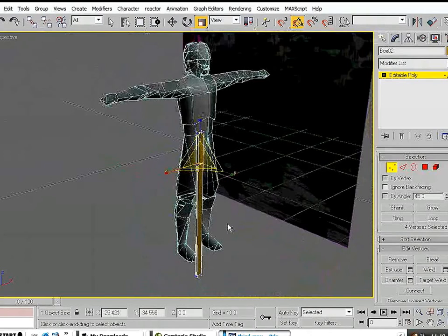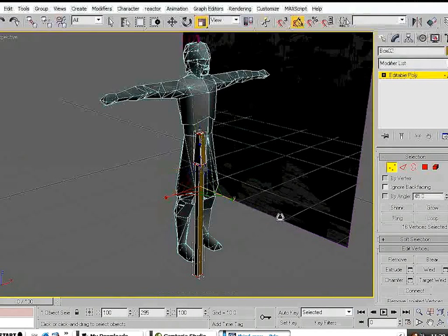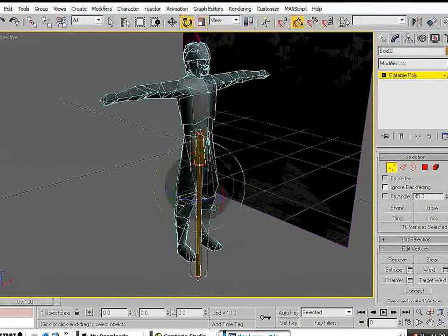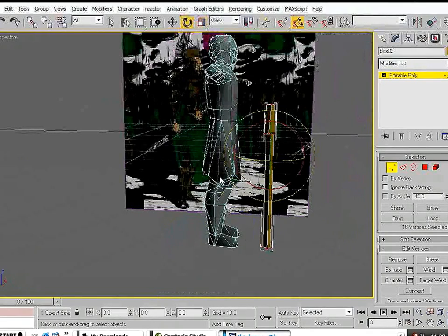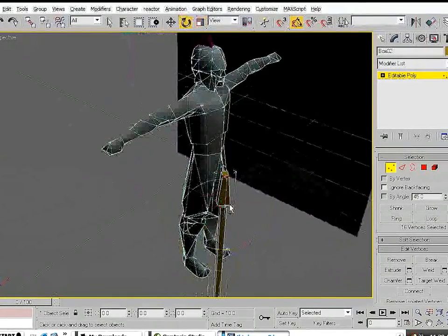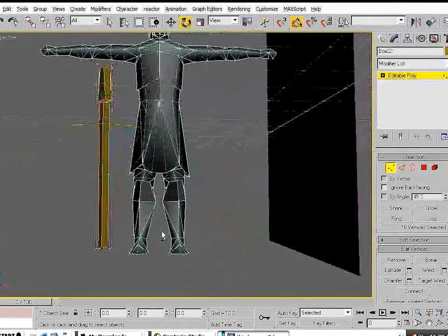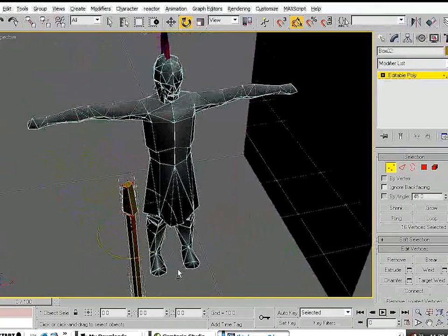So now what we're actually going to do is forget what I did before, pull it out to a square. I'm going to rotate it 45 degrees. Because just like the leg, if you have a four-sided figure that's supposed to represent a cylinder, you want the four-sided figure to circumscribe inside the cylinder and not outside of it.